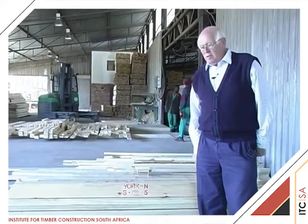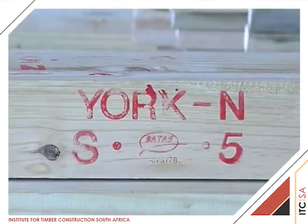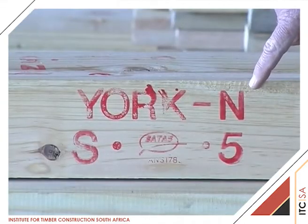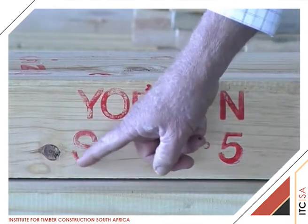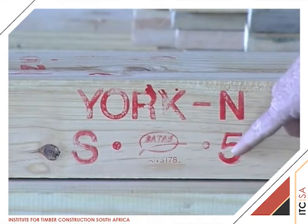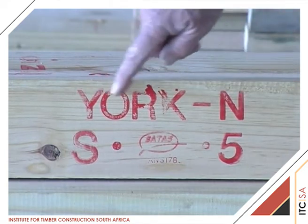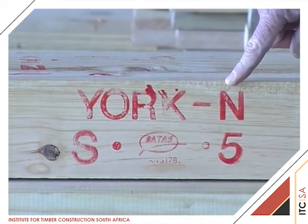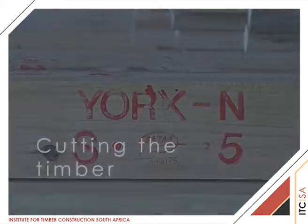It's important to note that all timber used in the manufacture of these roof trusses is graded according to an SABS specification. The S indicates structural grade and the 5 is the actual grade of the material. And the mill supplying the material, their name or their initial or logo would be produced on the timber.